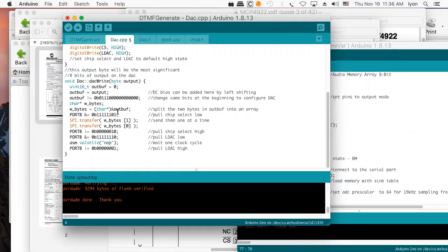Now, would it have made sense to call digital write, I don't know how many times, 1, 2, 3, 4, 5, 6, 7, 8 times in order to set the port and all the pins on the port? And the answer is no. That would not have made sense. So what we've done here actually was a far more efficient way to go.